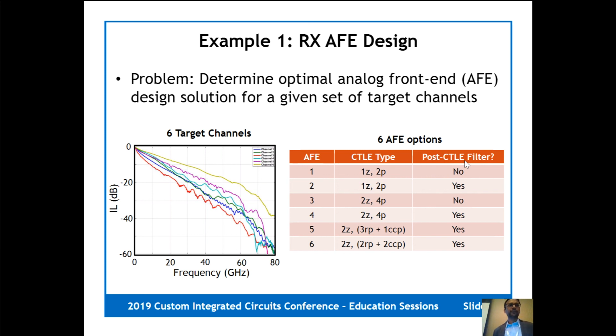I'll ask you. When we were in the transceiver speed limited regime and the channel bandwidth was high enough, we kept on using NRZ, and with Moore's law, the speed kept on increasing. If the channel bandwidth is not good enough, then there was a lot of work on making the channel wider bandwidth and things like that. So which regime are we in now? Are we receiver speed limited, and that's why we are going to PAM4? Or are the bandwidth limitations coming from the channel itself? And on that note, the next 2x is going to come from where?